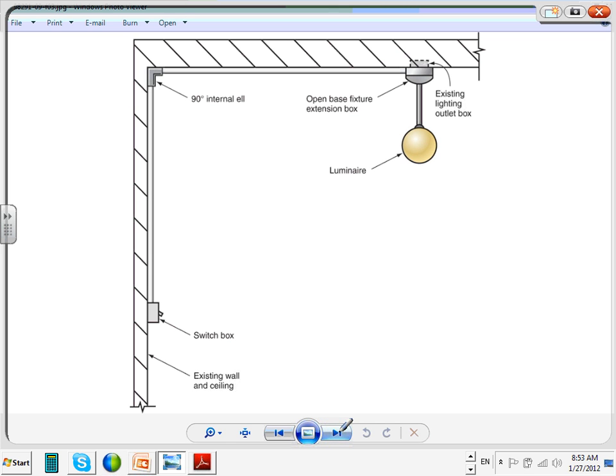I want to remind you guys, it comes with its own boxes and angles and switch boxes, fixture boxes. It's a whole wiring method. If you wired residential, you may have called it mold, and you can go buy it. If you don't want to fish things, though it looks ugly in residential, you can put it on the sheetrock and mount it and do the whole system. That's the residential part of it. But the commercial part of it could be a complete big, thick, wide version that you can install anywhere. Is it also known as wire mold? Wire mold is one type of it.